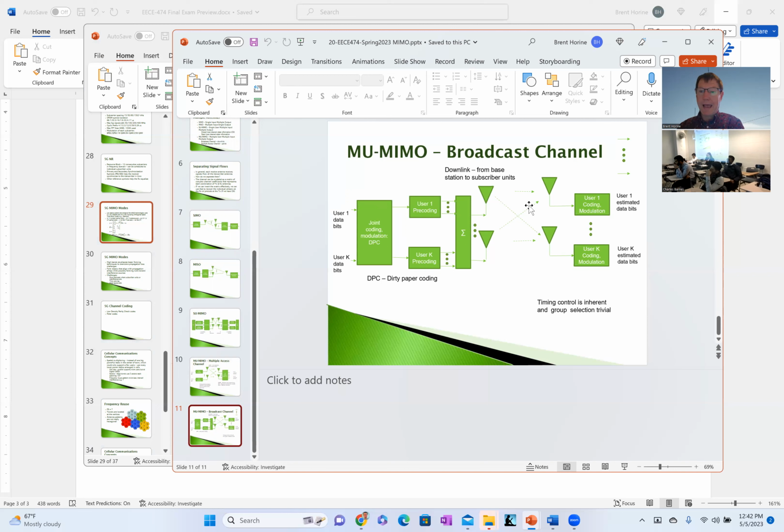Even if it's not that bad, our numerical ability to measure this channel and then invert it will suffer. The noise or the inaccuracies, numerical precision loss in doing that operation, is going to dominate over any of the differences that we actually get. So we actually want a rich multipath environment here, right, for MIMO to work.